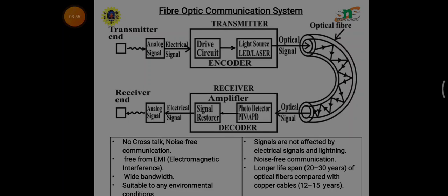Unlike attenuation, it does not decline the signal. However, it blurs it. For instance, a signal of 1 nanosecond at the transmitter will be spread to 10 nanoseconds at the receiver. Therefore the signals are not correctly received and decoded. Dispersion is classified into 4 types, which we already discussed: modal dispersion, material dispersion, waveguide dispersion, and polarization mode dispersion.